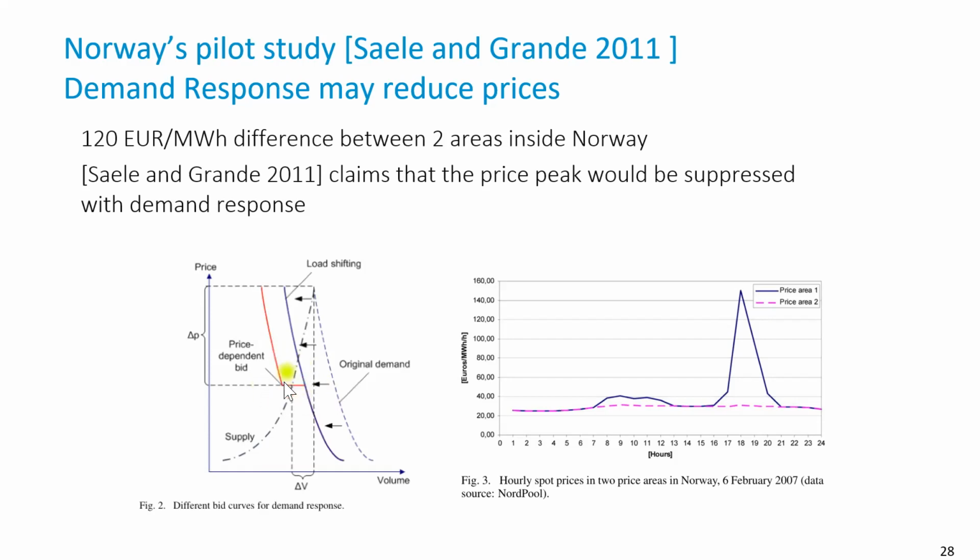So you see that when we're on the steep part of the supply, then a small change in the demand curve, of course, can change the prices dramatically here. Which is, of course, natural. That's what we expect. If the energy system is close to its capacity in terms of production, cannot produce more, or is producing more and more only at extremely high prices, then a small reduction can have a large impact on the price everywhere. So this is one of the motivations for demand response, and this is how this is exactly quantified and manipulated.